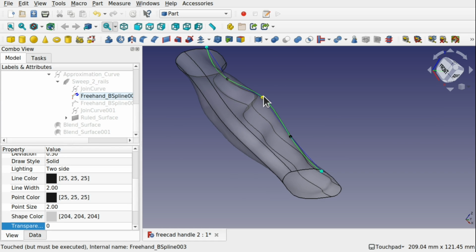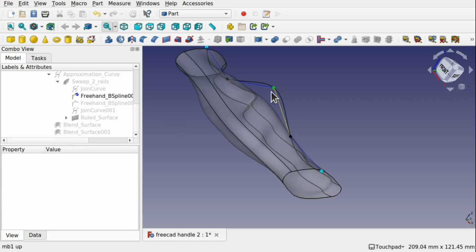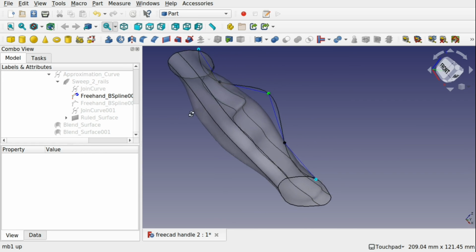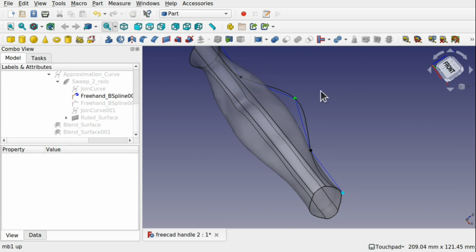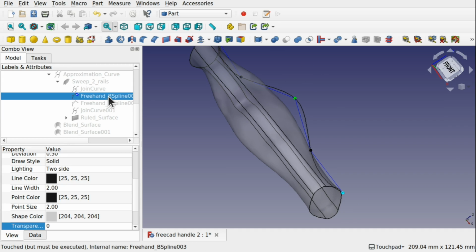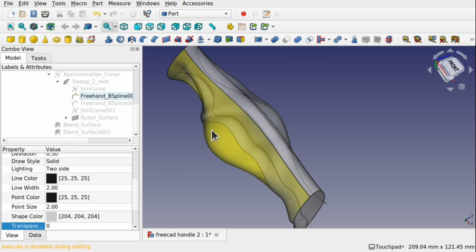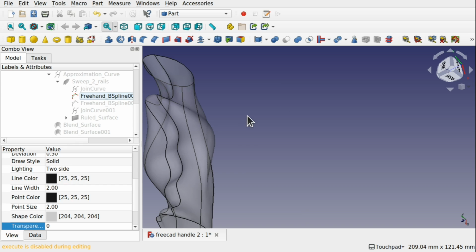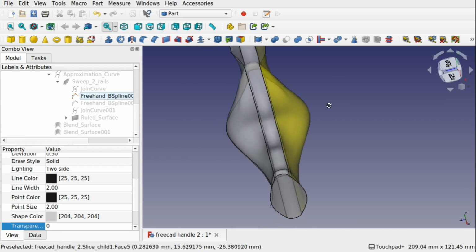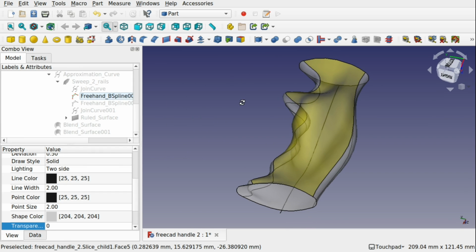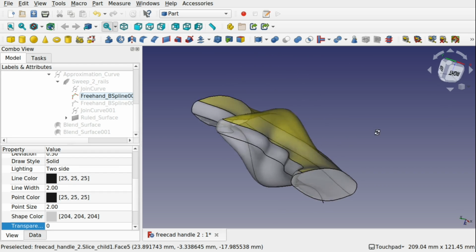and we'll flare out the body, bring this up. You have to be wary of where your extrude is. That's the reason why we created a larger extrude. Make sure the extrude is out here. Let's just double click that b-spline and you can see our body's flared out there. So that's a way of sweeping across multiple rails using the freehand b-spline along with coplanar surfaces to create a solid to allow for a fully parametric model that you can then take further in your design.